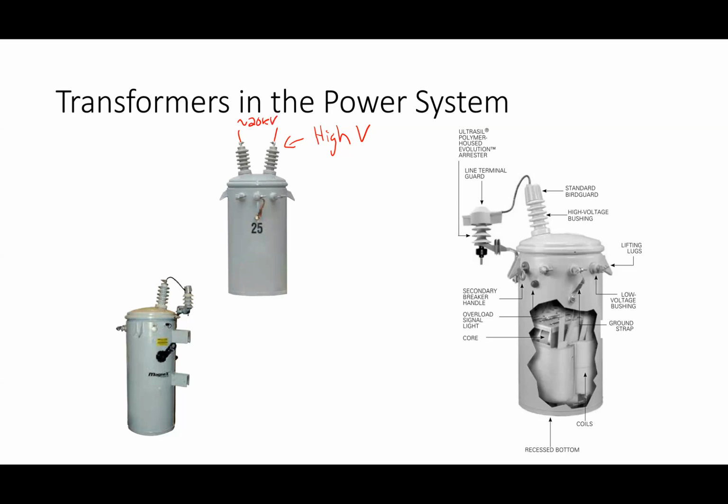All right. So if I look at the way that the power system works, maybe I should do this, right? As I go from the generators, that might be getting about 20 kV. And then it goes through a transformer, and I'm making a one-line diagram without ever explaining what that is. But 20 kV goes up to like either 230 kV or some number like that on the transmission grid. And then it goes down to different values, but let's say maybe 23 kV. That's what a lot of Duke Carolinas uses, is 23 kV.